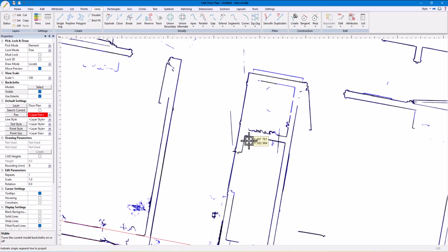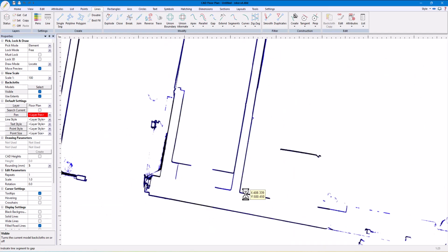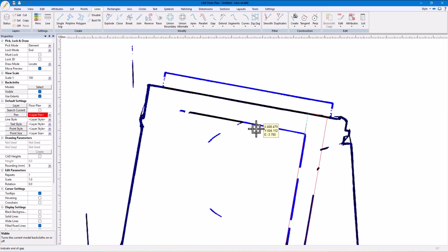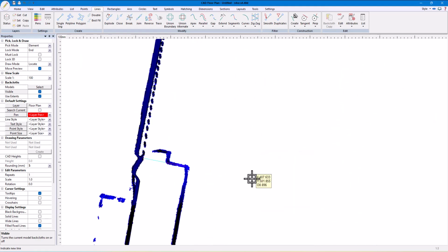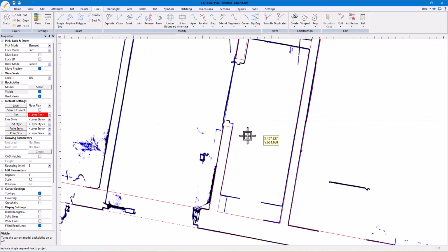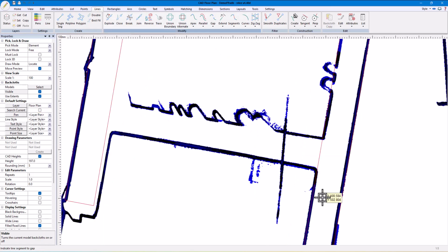This section has a small closet that means we need to join two extrusions in order to form the closed area. Initially, we will use the extrude command to go around its outside, making use of the appropriate lock modes where necessary. Then parallel the door opening as before and project it into the necessary wall segment. Now we can start the extrusion to form the closing wall of the closet.